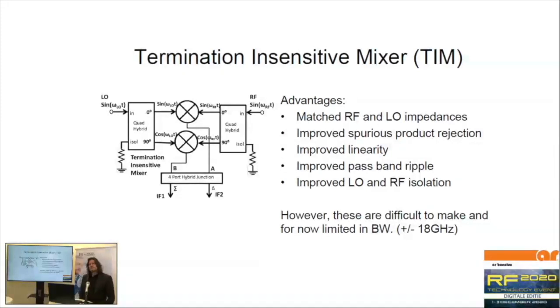Then the last one, which is a bit strange, but it's still in the same family as all the other ones: the termination insensitive mixer. A mixer is inherently a non-linear device, which means that if you put a signal at the entrance, either the LO, the RF, or the IF, it doesn't really matter, it will have a rather high VSWR, depending on frequency as well. That means power is reflected back into the circuit where it came from. And in some cases, that is not really wanted.